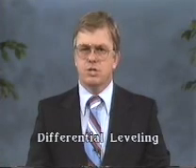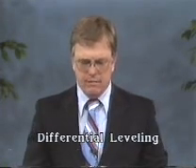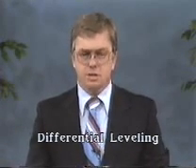Our third method of vertical measurement leveling is differential leveling. Differential leveling is a process of measuring the differences, the differentials, in elevation between any 2 points by spirit leveling. Differential leveling is broken down into different levels of accuracies known as orders. These orders are first, second, and third order.